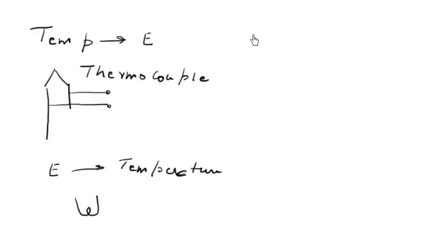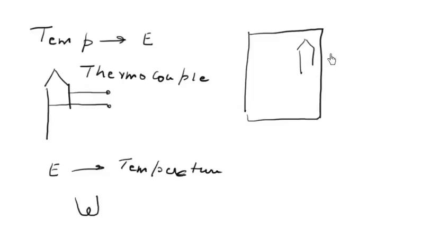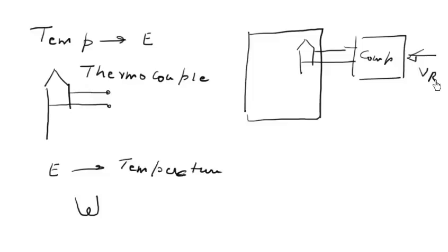think of one industrial application where, let us say, you have some chamber and the temperature in the chamber is required to be maintained at some specified value. So we have got a temperature transducer here. We take the output and then we have a comparator. This comparator will compare the output of the transducer with some reference value. So this will indicate the desired temperature.